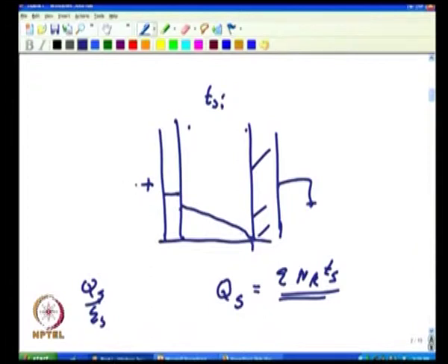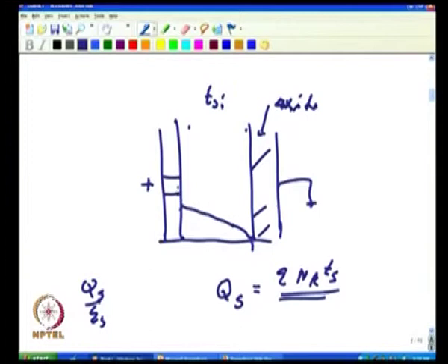Okay. Now, if I increase the gate voltage further, beyond punch through, what happens? There is no charge here, there is no charge here, there is no charge in the oxide, this is oxide. I hope you can read that. There is an oxide there. So, if I increase further, additional field lines will cross here, additional field lines will cross there, and since there are no charges here, it will be down by a factor of 3. The oxide field divided by 3 is the field here. So, if this has gone up, this will go up by the same amount, but by a factor of 3.